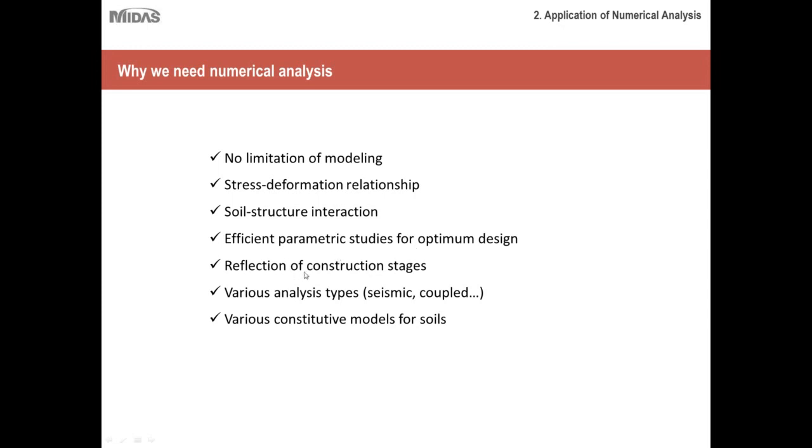And then reflection of construction stages. For larger scale projects that require multiple construction stages, numerical modeling can model each of those stages very efficiently. And then various analysis types are available to you. Among the unique analysis types are seismic and coupled, which analytical methods can't nearly handle. And then also various constitutive models for soil. Numerical modeling programs typically have databases of constitutive models at your disposal so that you have a constitutive model that best suits your project on hand.